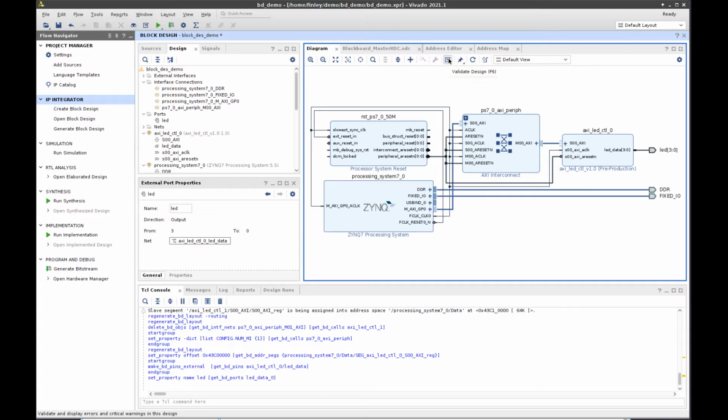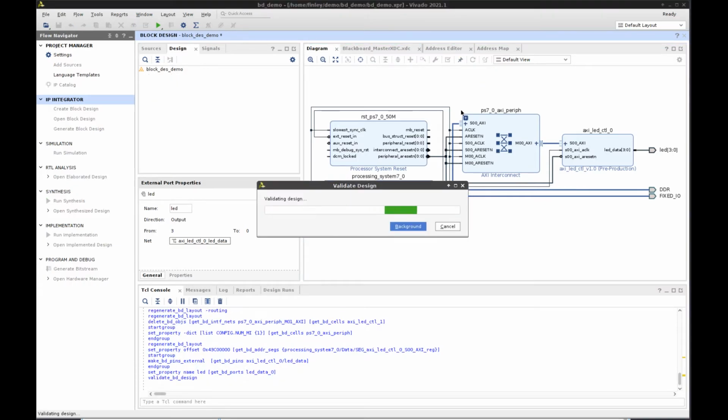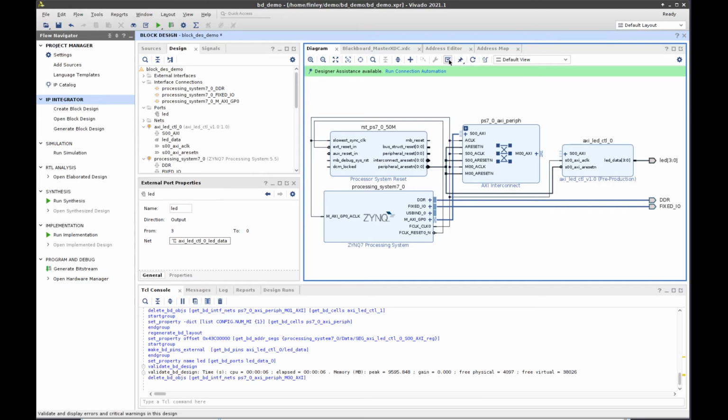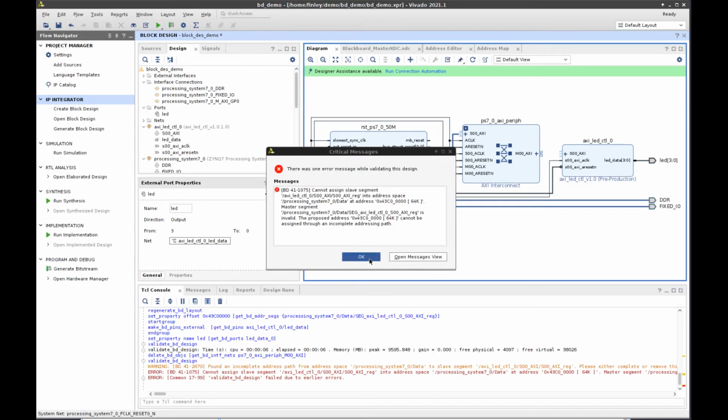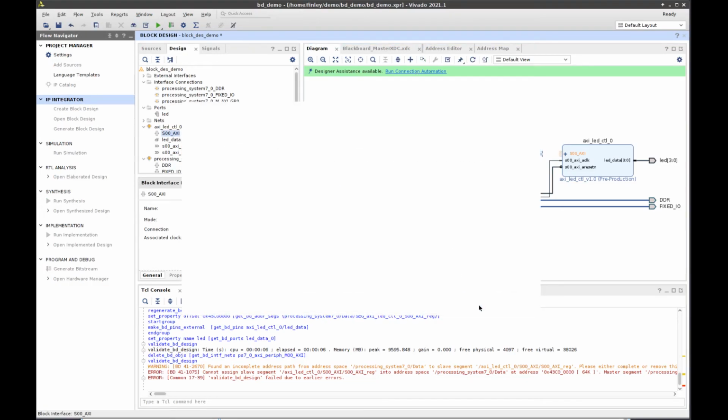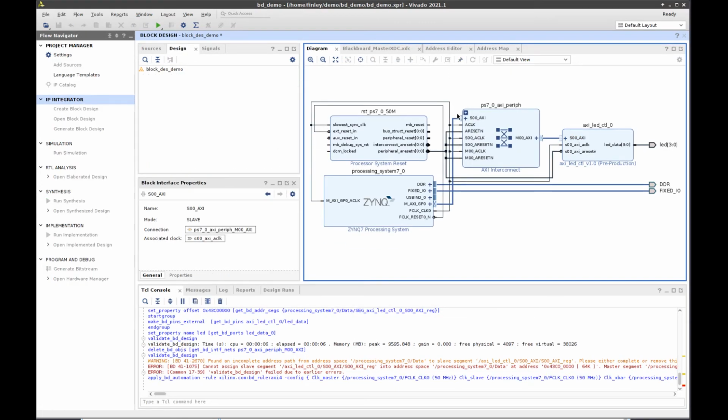Now in the block design we can click verify, and that'll tell us if we've hooked up something wrong, or if it's detected something. Maybe we have addresses overlapping in multiple IP modules. We don't, but you can see it's gone correctly. But if I disconnect, say, the wire between the AXI port or the interconnect and the module, the tool will tell me there's an error in there, and I have to resolve that before I can synthesize it onto the hardware.